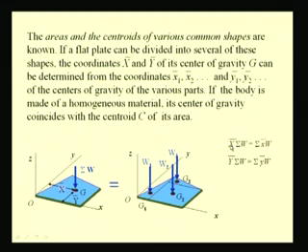So, what we have is x bar sigma W equal to sigma small x bar W, where small x bar is the location of the centroid, mass center and center of gravity if we assume homogeneous materials, and in the same way y bar sigma W is equal to sigma small y bar W.